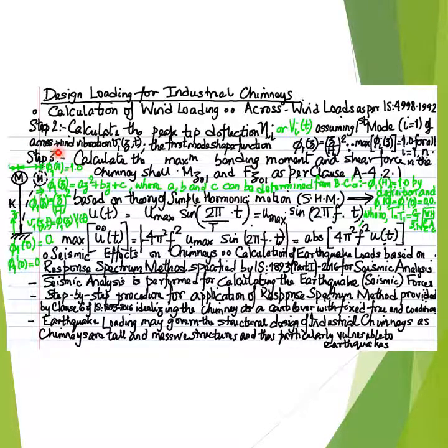Noting that the maximum value of the deflection at the free end of the single degree of freedom model that is used to idealize the chimney shell is 1 or unity for any mode shape, including the mode shape 1, and the base of the cantilever, that is the base of the chimney shell at the ground, is idealized to be fixed against deflections as well as rotations,